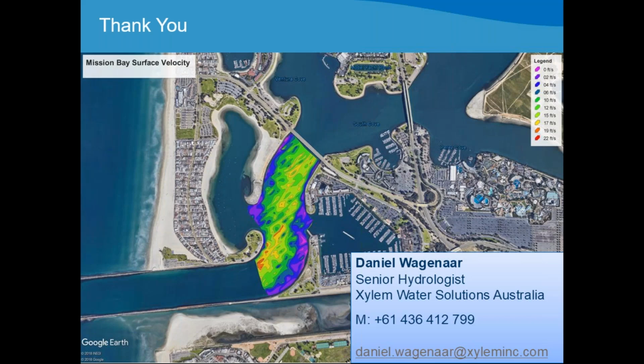Daniel, if you use the USGS option in RiverSurveyor, does it detect if it's an S5 or an M9 and set the blanking distances accordingly? Yes, RiverSurveyor Live automatically detects if it's an M9 or S5, and based on that will apply the blanking distance.